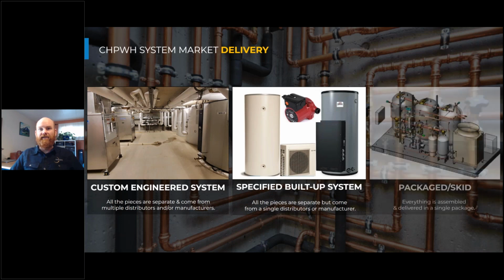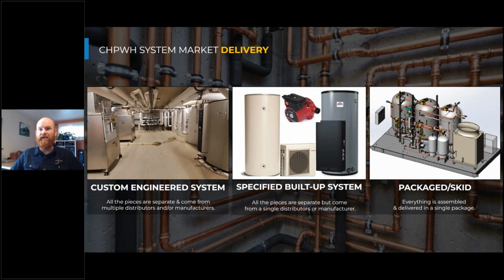And then the latest and greatest, which is still new, but Mitsubishi was at AHR this past year with one of these packaged skids, is a fully packaged system where everything is assembled and delivered in often a single package or two packages that kind of meet up together to serve the water heating load in the building. And so here you're going to have the storage tanks, the temperature maintenance system, a heat pump, and a control system all packaged together.